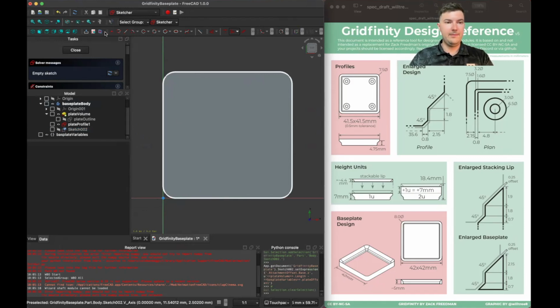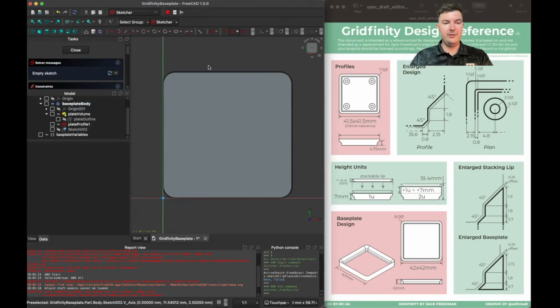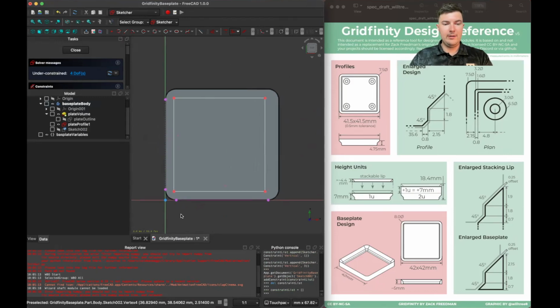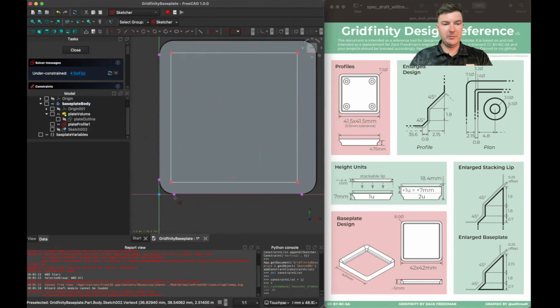Now what I can do is I'm wanting to view the section, and this time I'm going to want to reference external geometry. So there's a toolbar up here, or I can press GX on the keyboard, which is what I just did. And I want to reference this edge and this edge. I'll be drawing another two-corner rectangle. And I want my smart dimension tool.